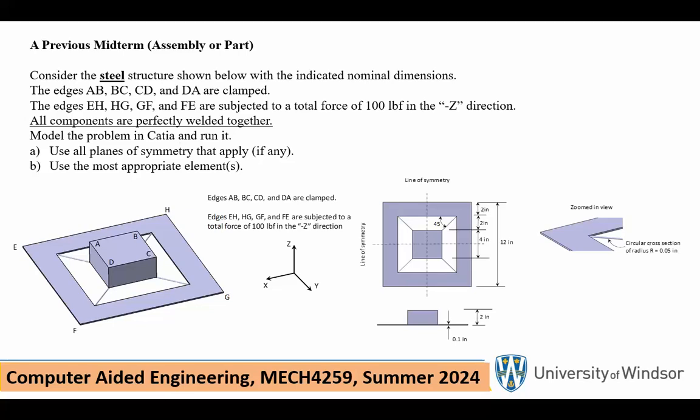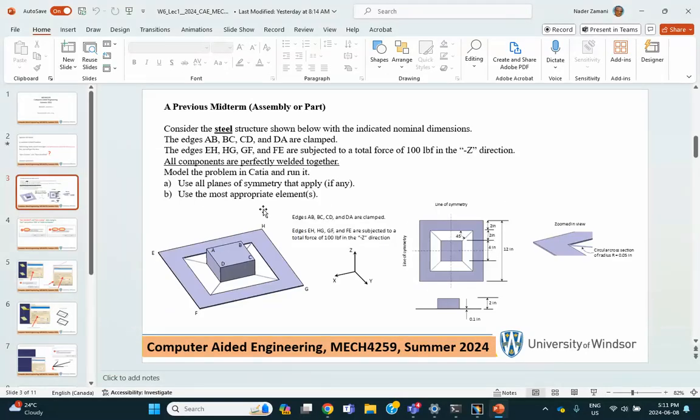However, if this is to be a beam element, there is no way you can cut a beam element through its length. Therefore, because this is a hybrid problem, you should take a 90-degree sector as opposed to a 45-degree sector. Okay? So that's pretty much it. So let's go ahead and do it. We'll come to these other issues later on.